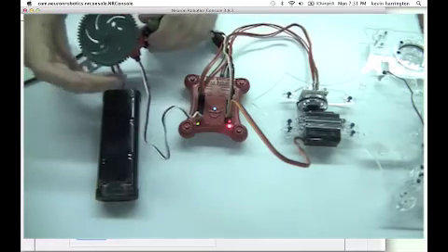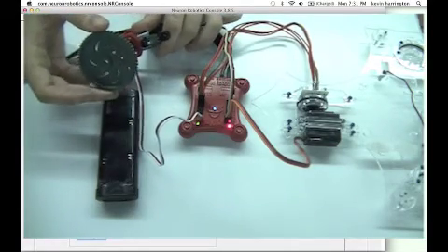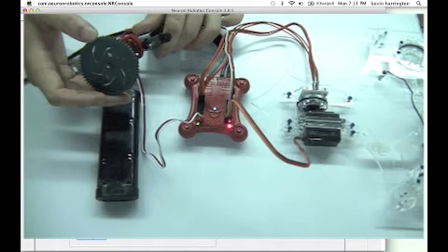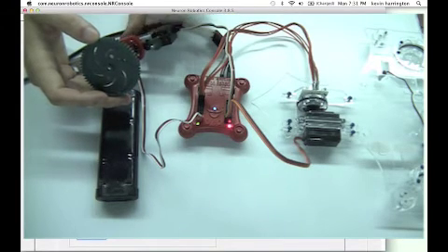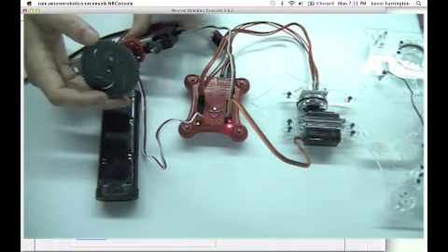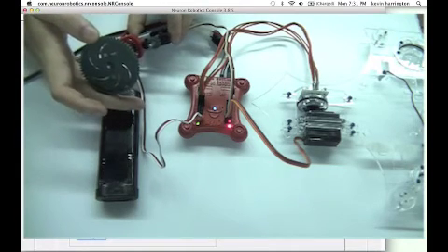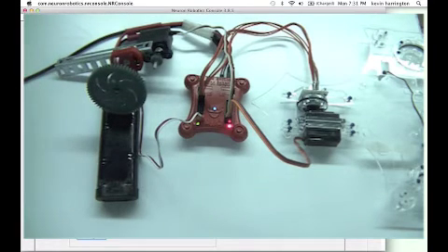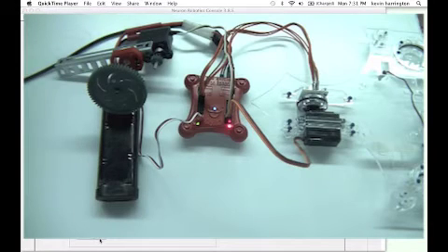What we want to check with the analog, since it can't spin continuously, is to see if the system is diverging to begin with. So what we'll do is move the sensor and notice that the servo is driving the sensor further away from convergence. This means that this system, like the other one, will also need to be inverted. We check the invert box and reconfigure.